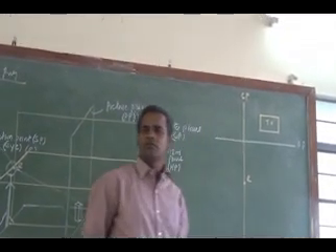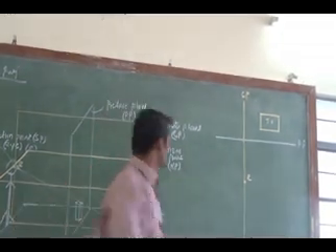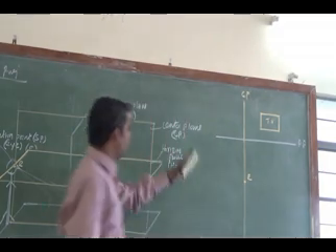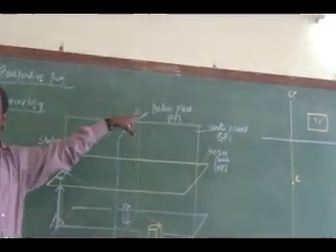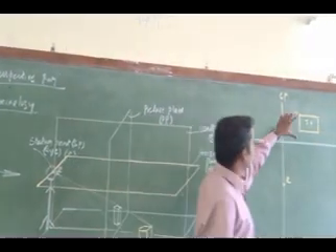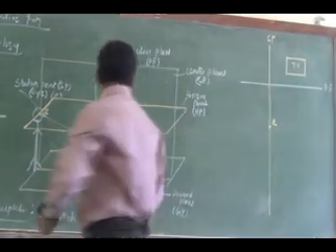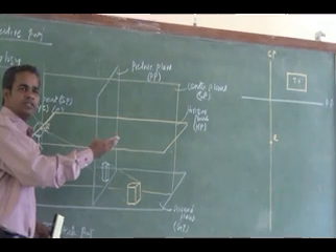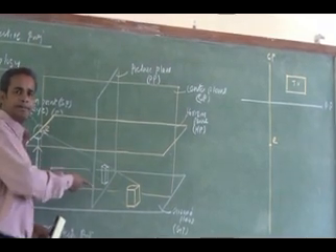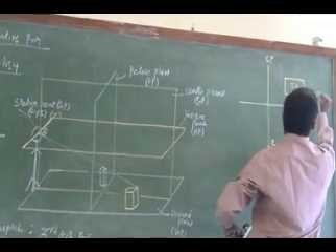What is the notation of the top view for any point? Without dash. So the front view notation we will have with dash. Now can you represent the positions of these in my top view? So what is this position? The object, the size will be given. Where the object is normally kept, is it behind the picture plane or in front of the picture plane? Behind the picture plane. So this distance will be given in your perspective problem.